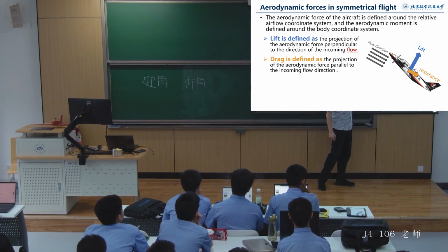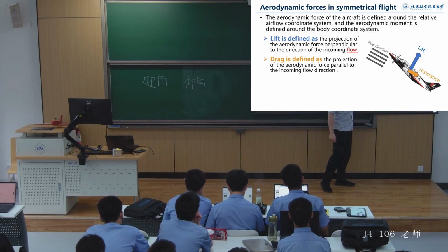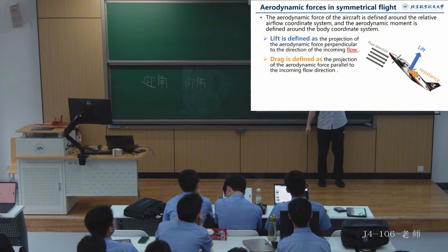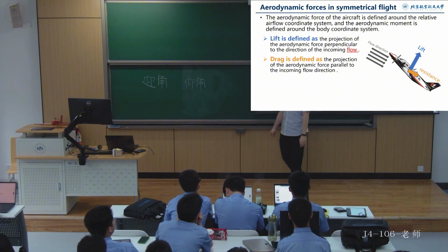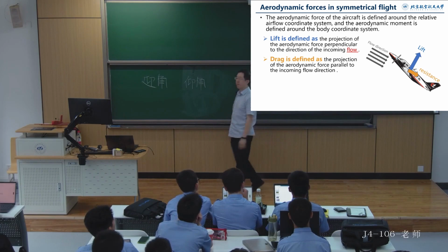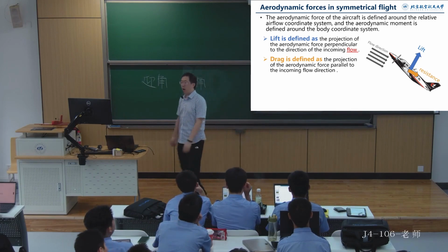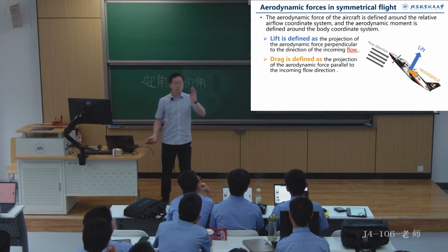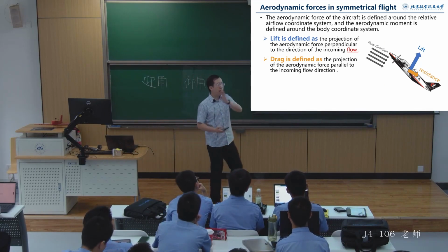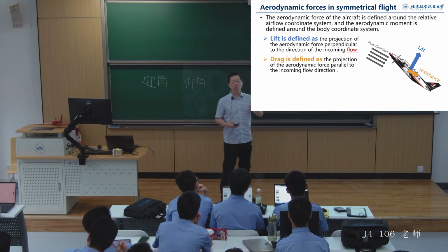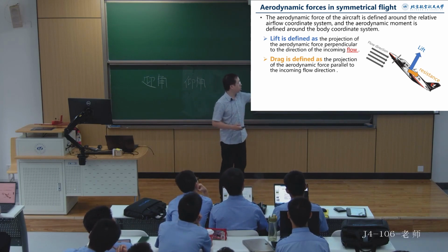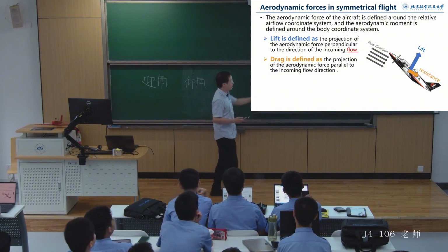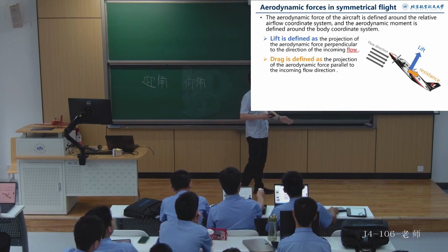Alright, when we talk about the position at this point, besides the influence of the force, what additional impact might it bring? It's an important concept we mentioned in the first lecture. When we move the force parallelly, besides transferring the force, we must not forget there's another important aspect: the moment. Now let's assume the airplane is flying in a symmetric state, meaning without any side slip.